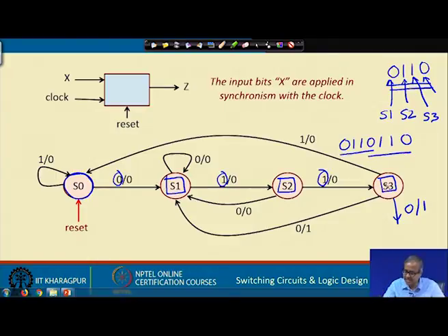Now, when you are in S3, what does that mean? You are at this point, you are in S3. Now, a 0 has come. This 0 is also S1 for the next pattern. So, instead of moving it back to S0, we are actually moving it back to S1, because you also need to check the next overlapping pattern, and it may start here also. So, you are actually in S1 for the next pattern.